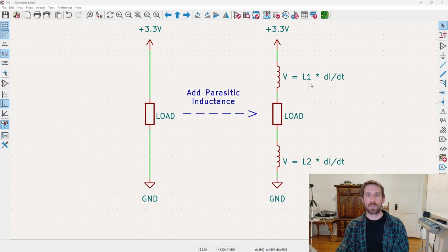So this one here connected to power is pretty well understood, even by newbies, about what to do, even if you don't fully understand it. This is where you get into short traces, wide traces. Don't forget the decoupling caps. You need them. And then the bulk capacitors. So I don't want to linger on that topic just because most people do the right thing there. Repeat, most. This board I'm working on, oh goodness. But that's another story for another day.